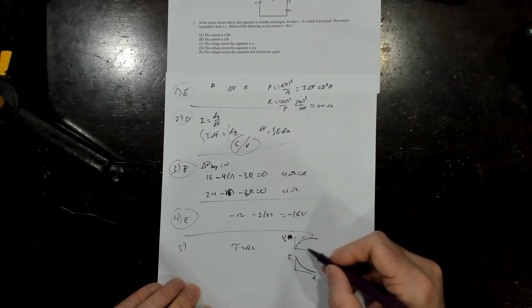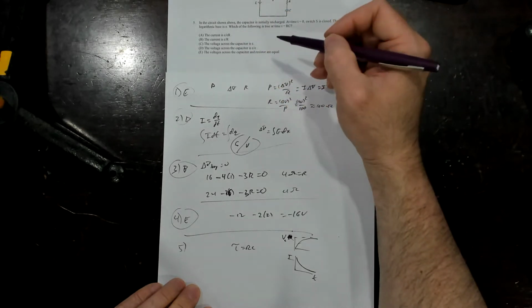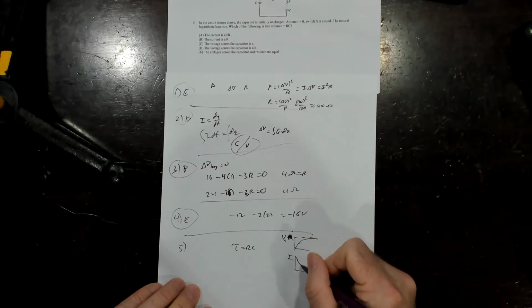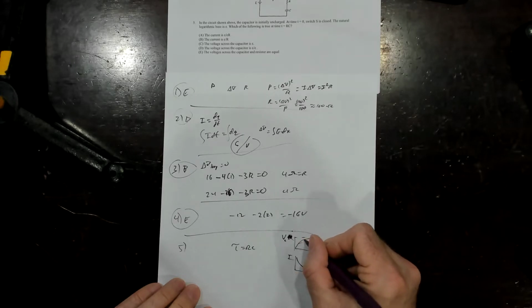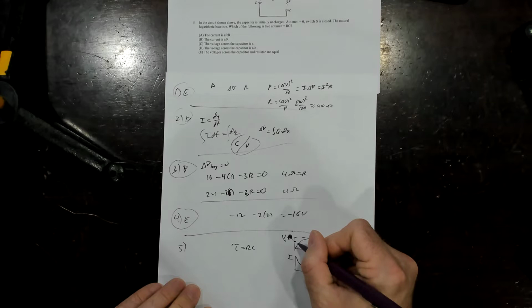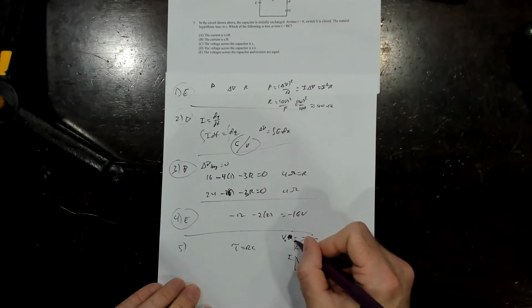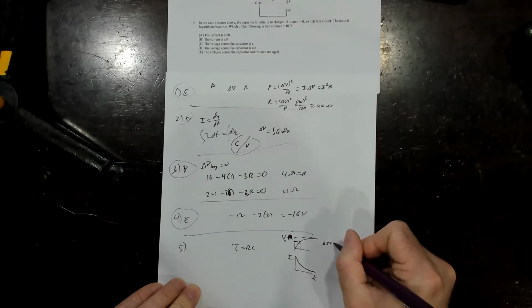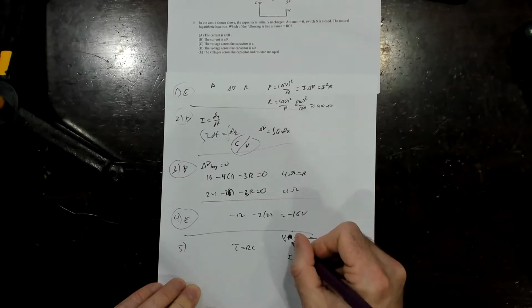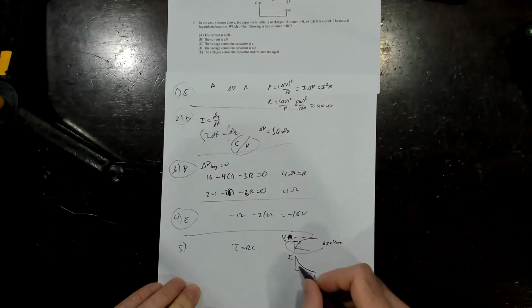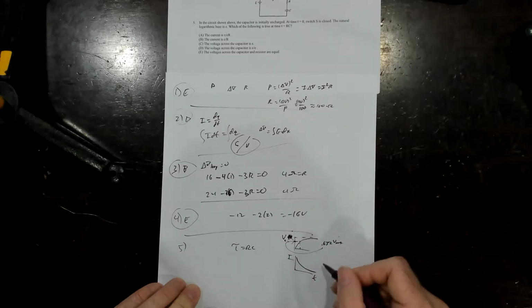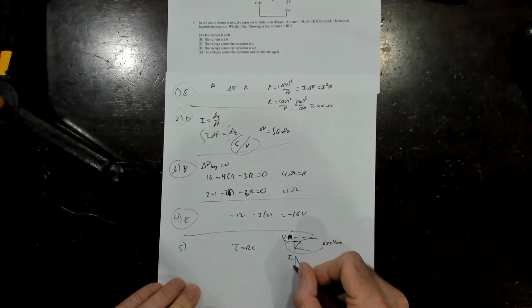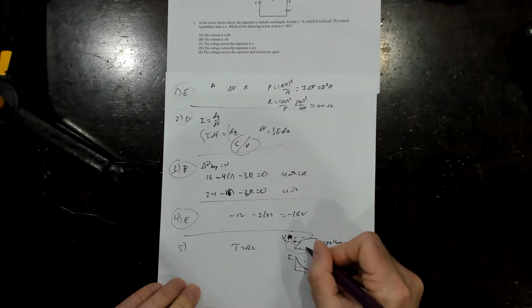They're asking me questions about what's going to happen. The time constant is the time it takes for you to get to 63.2% of the max value, right? So when time is the time constant, I'm at 63.2% of my Vmax. That's this value here. And this one, I'm dropping down, so I'll be there at that same time constant.